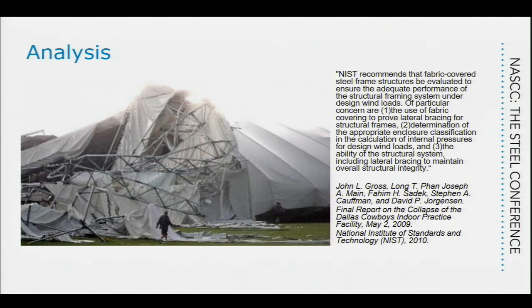If you have a chance to take a look at that, the report from the National Institute of Standards and Technology, one of the conclusions was, we don't know if the membrane can brace the steel structure. And when you ran the analysis, assuming that the membrane braced the structure, you would get it to pass. Everything looked beautiful. And then you remove that bracing, and all of a sudden, they were overstressed by 500%. This one killed 2 people, so it's dangerous.